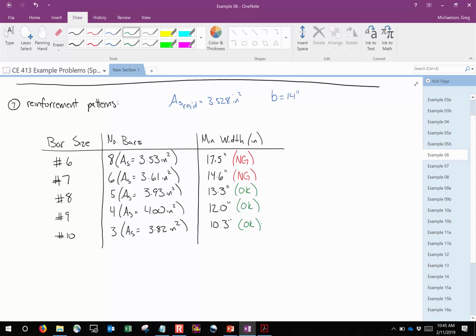Looking at the number 11s, the number 14s, and the number 18s, is there any iteration that's smaller than this number but bigger than that one? No, right? Because the number 11s go all the way to 4.69. Then you've got 4.5 and 4. This is the most economical choice, right? So here, yes?